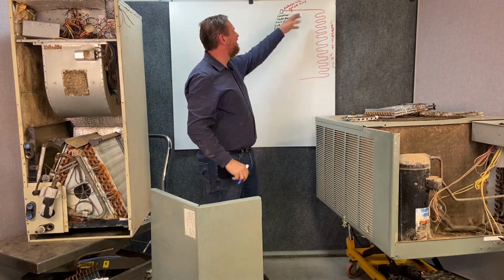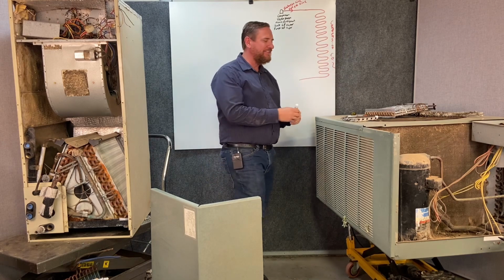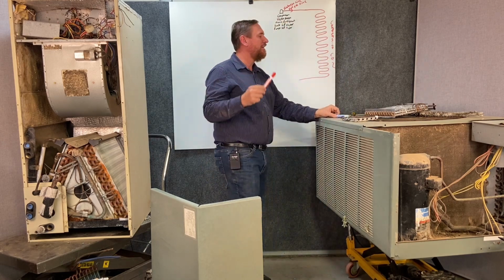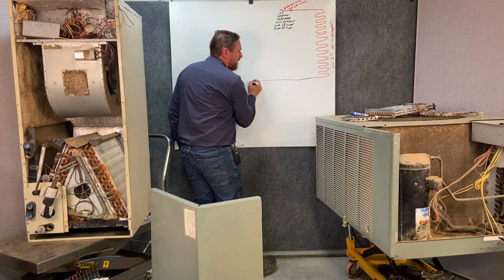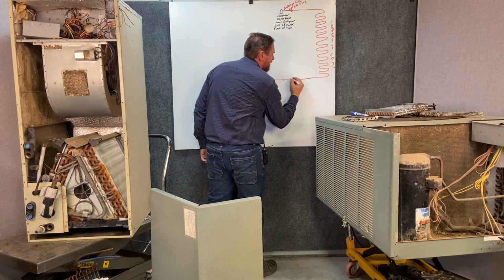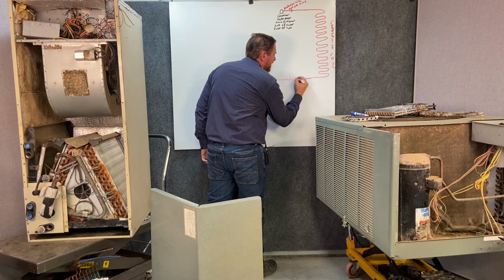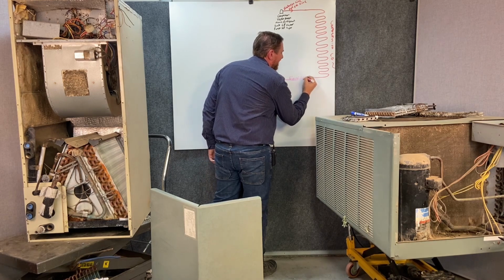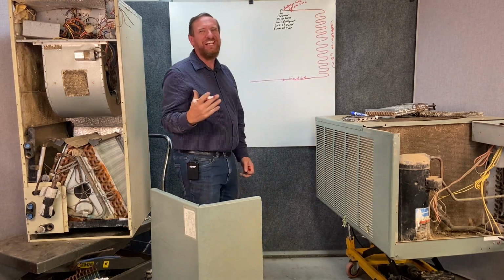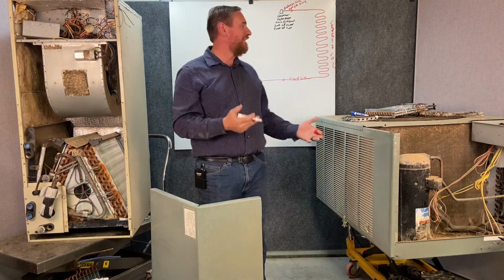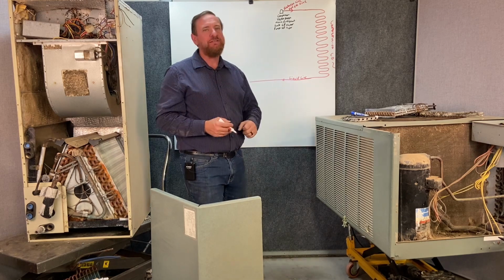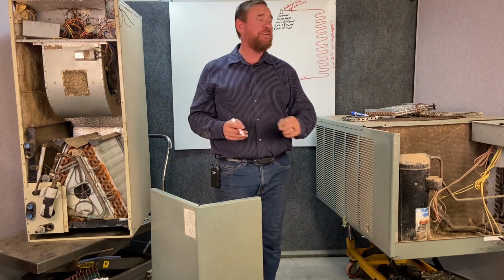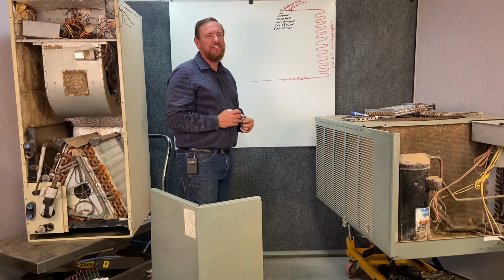So we go into the condensing coil as a hot gas. We're going to come out of this condensing coil, and we're still going to be red. This is where we're coming out of the coil, and we're going to have a very special line right here, and this line is going to be called a liquid line. And luckily, liquid line is the only line that we have one name for. So liquid line, it's fantastic. We're going to add more to this about the state of refrigerant in this line. It's very, very important. But to start off, it is a liquid line.